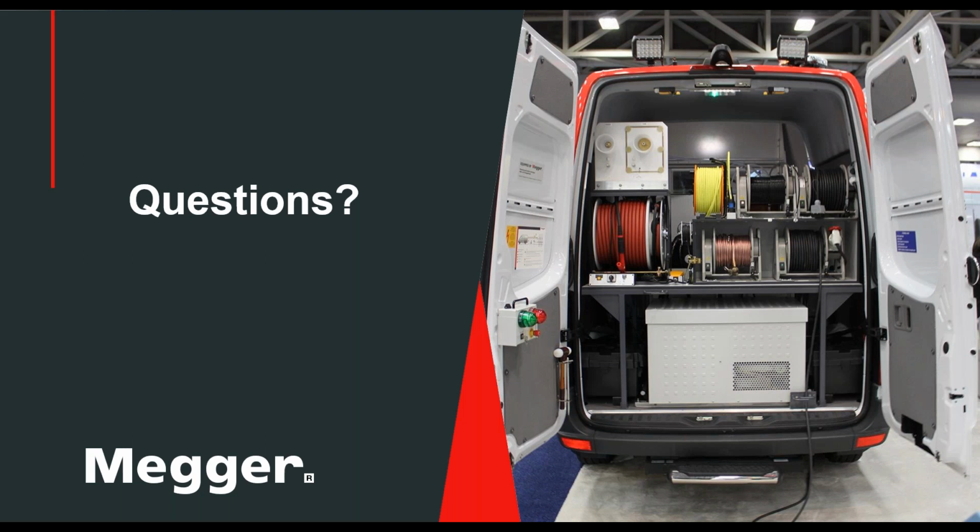So there is a good argument to be made: just don't thump on a fault. Use first the proper TDR arc reflection tool to pre-locate it, and then do the thumping for the pinpointing. And then you will do very little damage or no damage, because the damage will occur at the fault. So you don't really care about that.